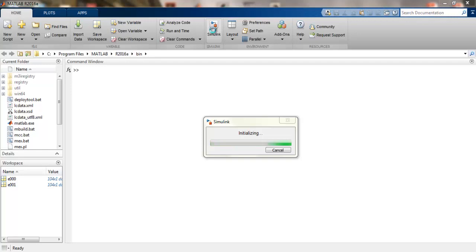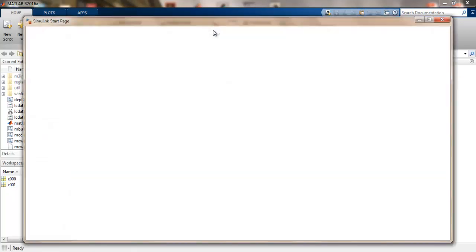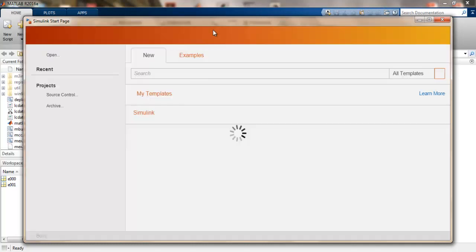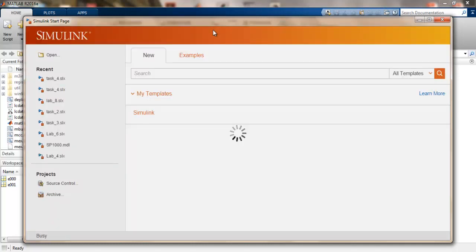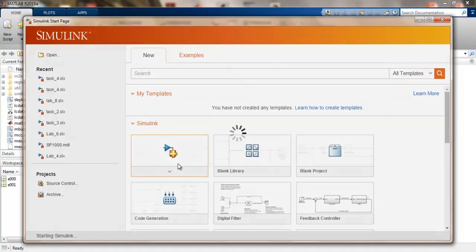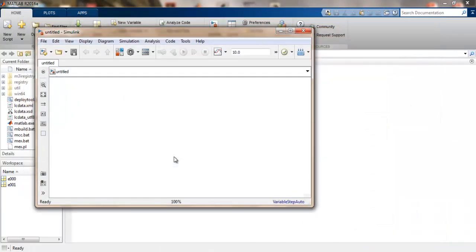Okay. Since we have derived a first-order transfer function, we can now open Simulink to create a simulation of a simple feedback loop to make a properly tuned PI controller. On a blank model, create a feedback system as shown here.